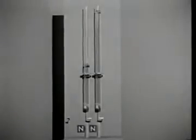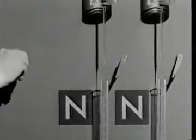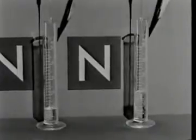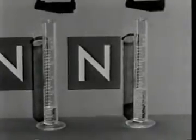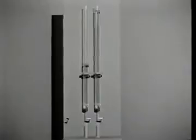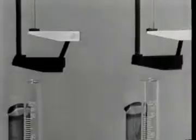The basic phenomenon occurring here is more easily seen if the pressure head remains practically constant. These are two identical burettes containing the same Newtonian fluid. The pressure head in one is twice that in the other. The ratio of rates of flow is also 2 to 1, as we expect from Poiseuille's law. But if we charge both burettes with the fluid exhibiting nonlinear behavior and apply the same ratio of pressure heads, the result is quite different.